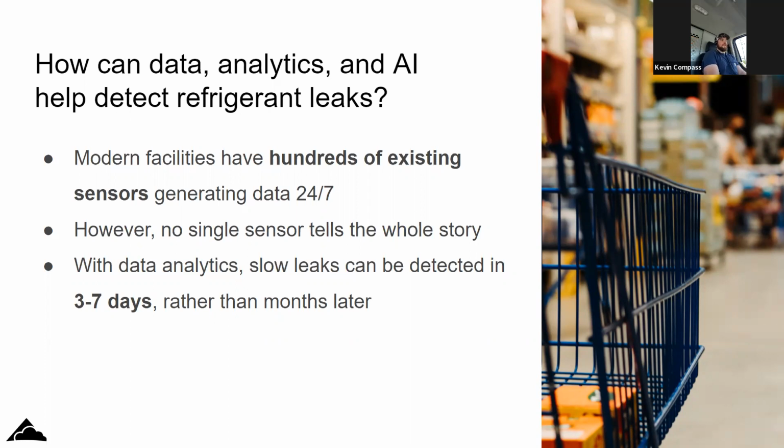That's where the data analytics comes in. Are we actually losing refrigerant? Can we look at the graphs and pull them? Or did I just go into split and just not pump out fast enough? I have a big 12-fan condenser and I just didn't pump out fast enough.